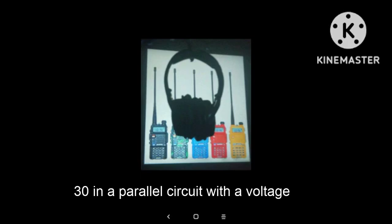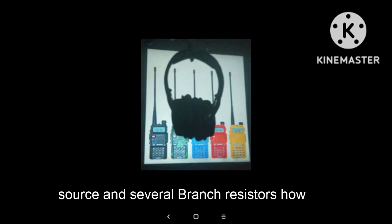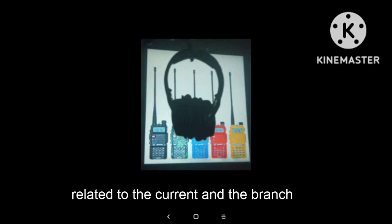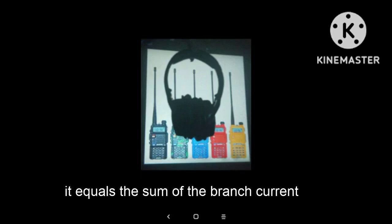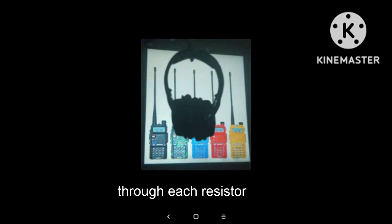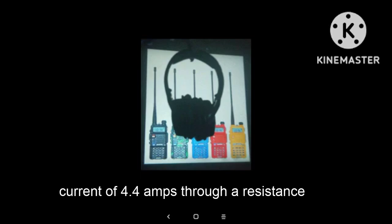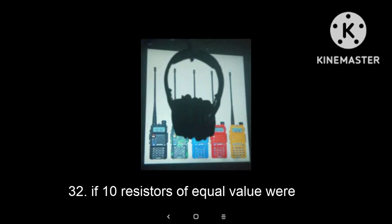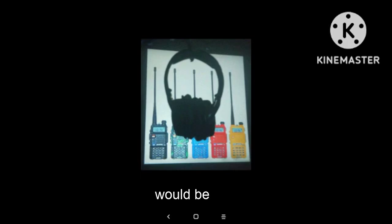30. In a parallel circuit with a voltage source and several branch resistors, how is the total current related to the current in the branch resistors? It equals the sum of the branch current through each resistor. 31. The voltage required to force a current of 4.4 amps through a resistance of 50 ohms is 220 volts. 32. If 10 resistors of equal value were wired in parallel, the total resistance would be R divided by 10.